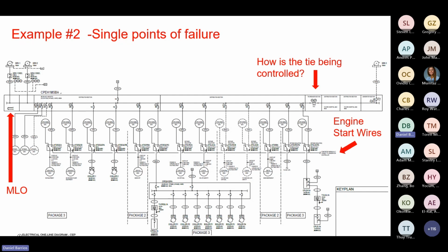And kind of getting to some of your NFPA and your NEC requirements, the engine start wiring. You notice that in this case, because of the limited amount of space to bring those wires into, all of these transfer switches are daisy chained with their start circuit, bringing in a single pair of wires. Well, if you need to have those separated out, you may have exceeded the capacity.